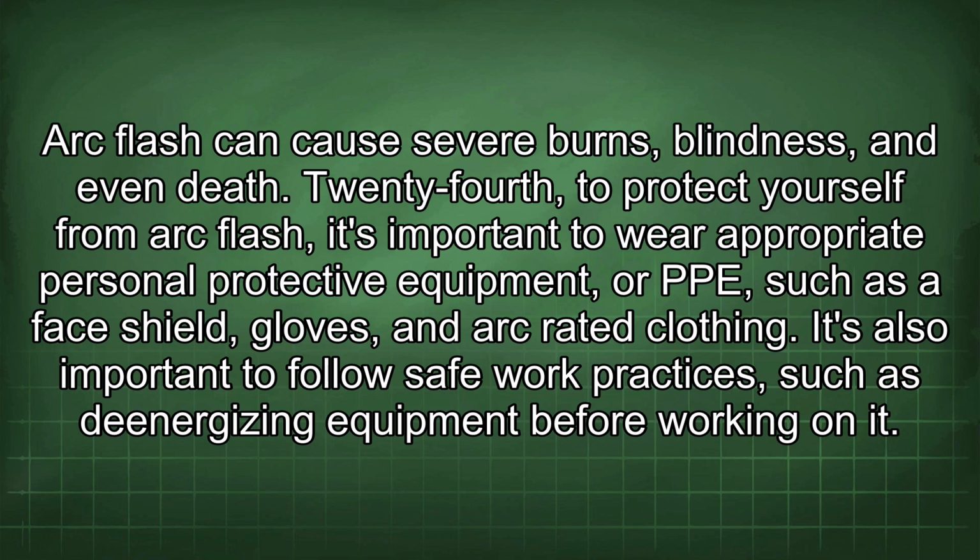24th, to protect yourself from arc flash, it's important to wear appropriate personal protective equipment, or PPE, such as a face shield, gloves, and arc-rated clothing. It's also important to follow safe work practices, such as de-energizing equipment before working on it.